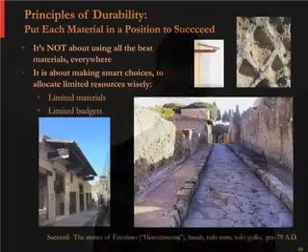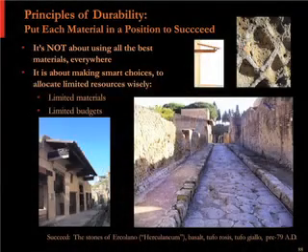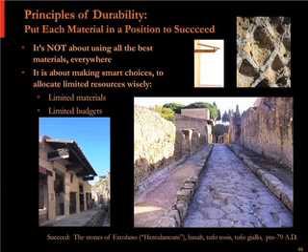So the way to deal with that is shed and shelter, and that's what we're seeing in those Tudor houses and in those step facades in Venice, and really even in the windows that we were looking at at Palazzo Bronski, is the overall facade form, the roof overhang, that beautiful eave detail, the hoods, the sills, and all the ledges and the band courses on those streetscapes are all managing water and shedding and sheltering.